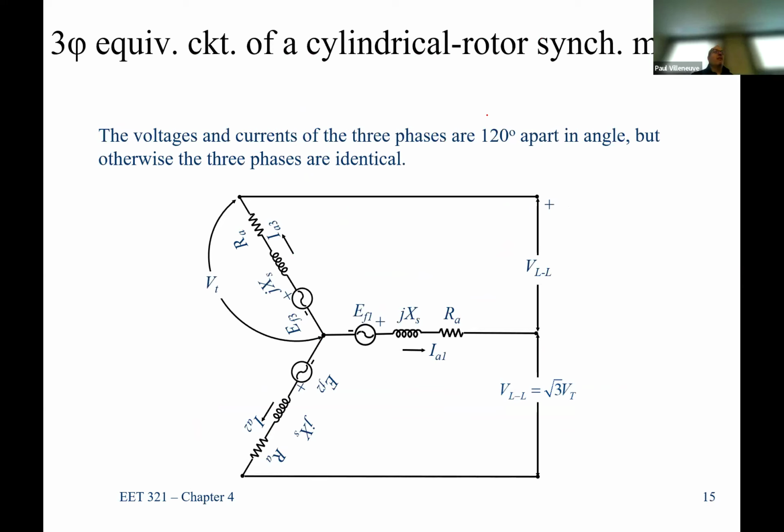A three-phase machine means we have three separate windings that are completely independent of each other until they're connected internally or externally. If you were to buy a generator and look at the connections, the first time I saw this it blew my mind. That's what I saw for a connection diagram. It's like, what the heck is that? Why do I have 6 wires coming out of the generator? Because you have 3 separate phases, and it's only when you connect them together that you show the connections.